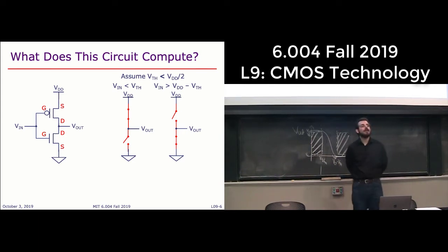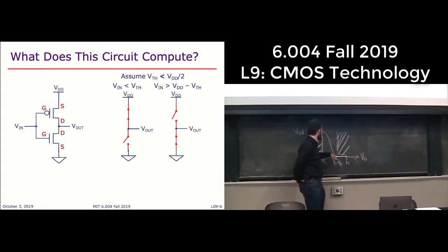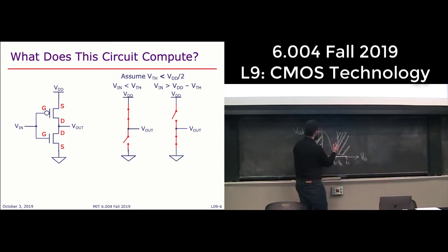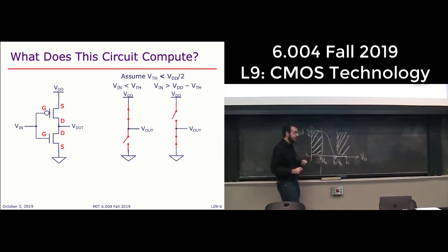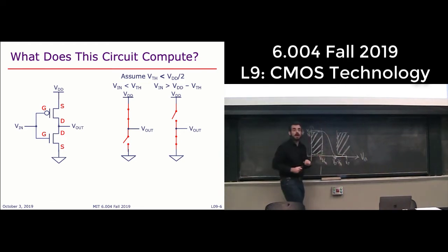It's the amount of noise that you can tolerate from an output to a downstream input. So that's the smallest of the differences between your output and your input levels. To have high noise margins, you want these two levels to be as far away as possible. You want the difference between VOL and VIL to be large, and the difference between VIH and VOH to be large.